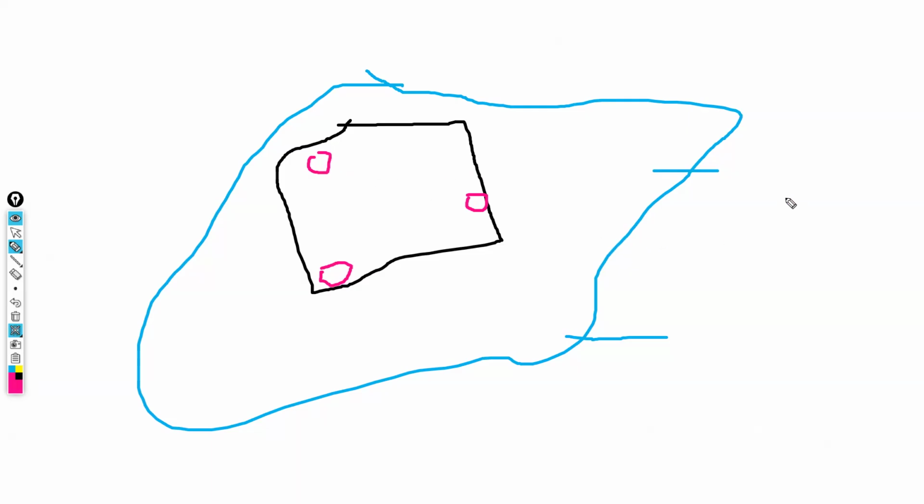In increments from 0 at the surface, you get results of the DCP. So you get results at a depth of, let's say, 1 meter below the ground, and then DCP results at a depth of 2 meters and maybe up to 3 meters. This is for one trial pit. You do the same for this trial pit and also for this trial pit. You have different results as you go down into the ground.